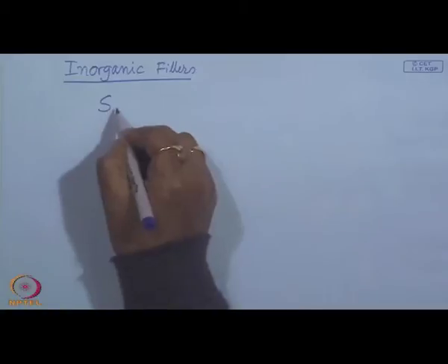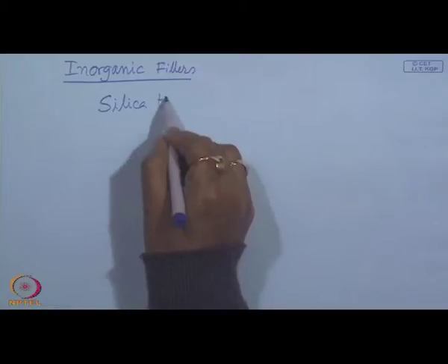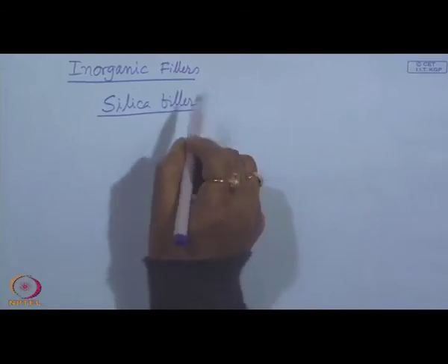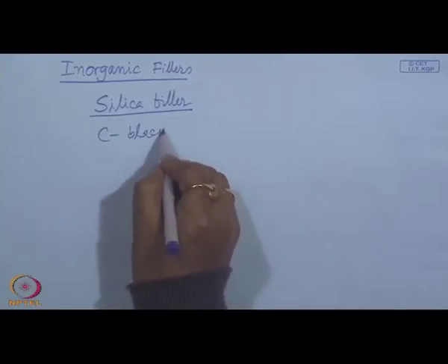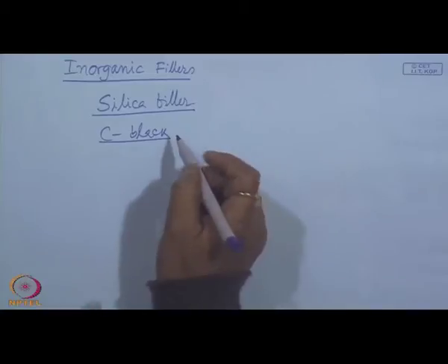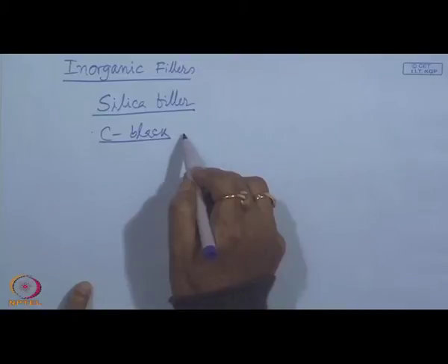Now, these inorganic fillers, for example silica filler, are not compatible with hydrocarbon rubber, whereas carbon black, as I discussed earlier, is very miscible and compatible with these hydrocarbon rubbers.